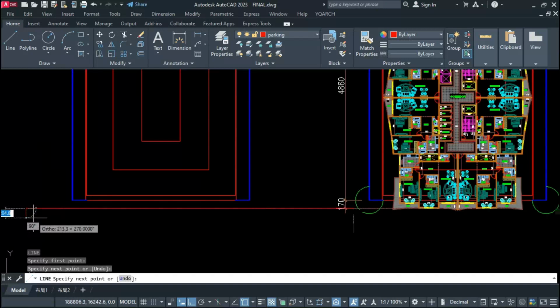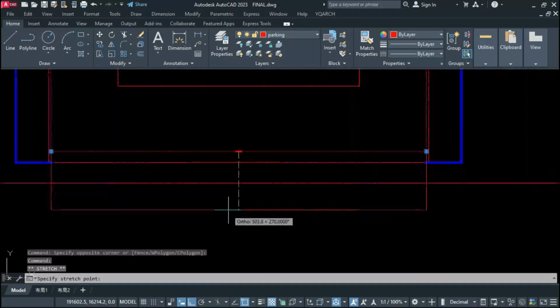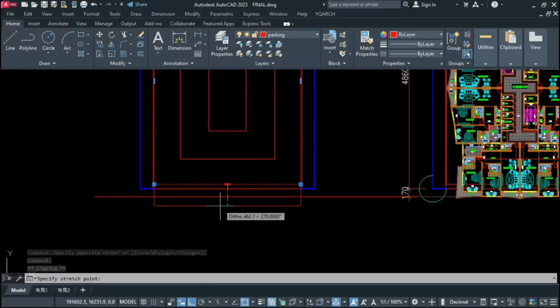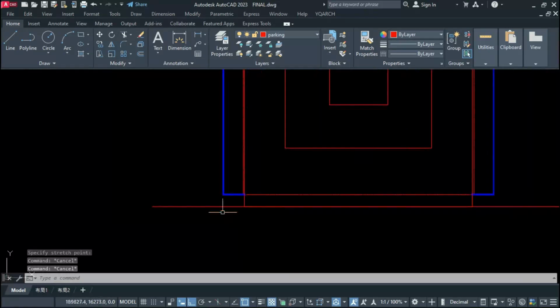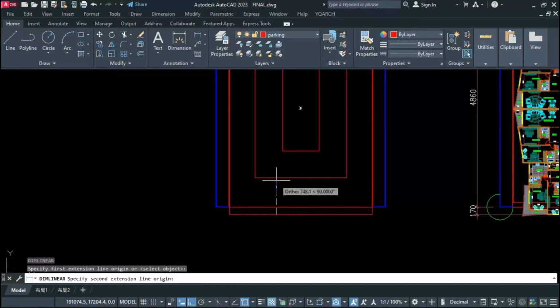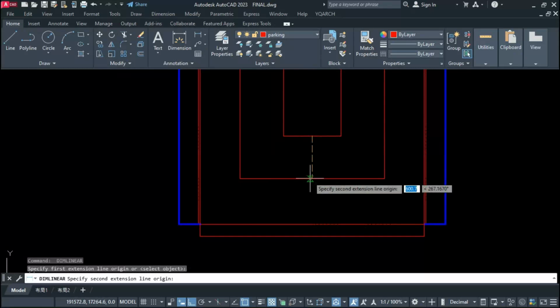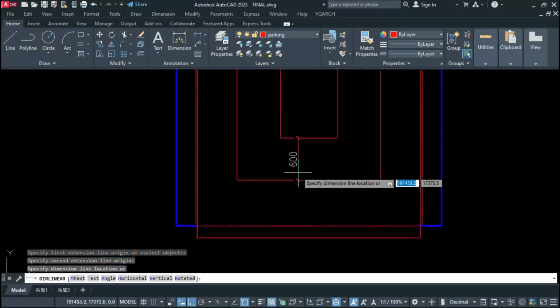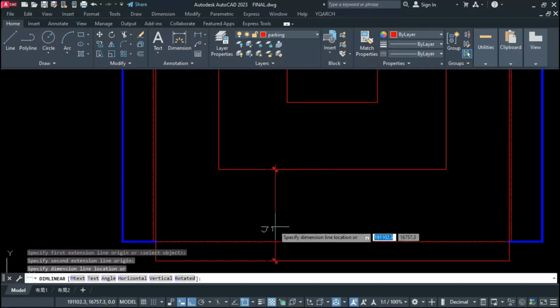Let this straight line be the reference. Okay. This is an imaginary line. And let this here come straight up to here. Our car parking area will cover up to this point. This is okay. Now if you take dimension, we are getting wider space. So we can stretch this part. We are getting 600 centimeter. So let this part stretch around. Minimum we need 550. So we are getting 817. So this is wider space.